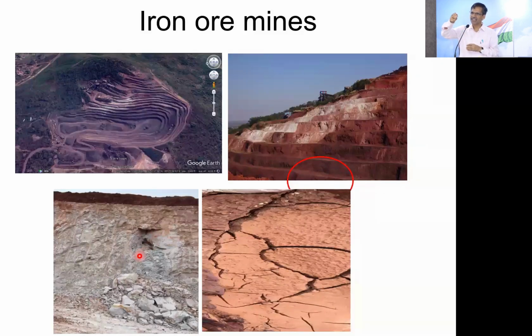This soil, whatever it is, is called dispersive. Once water comes in contact with it, it will disperse, I mean it will make a hole and pass through. So this is not a slope failure. When I visited for some other purpose, they said this is what they are trying to handle, it is failing. This is not a matter of concern. The slope failures are small, these are local failures. If you give it a small strength, it will be stable.